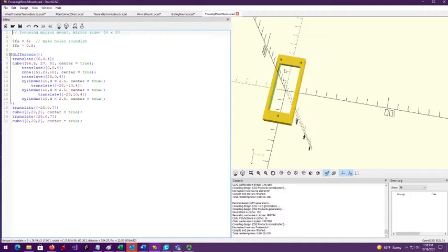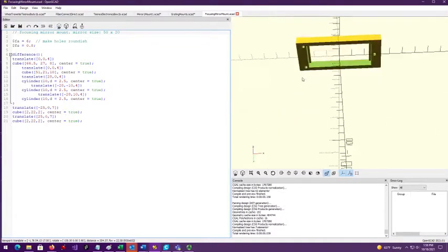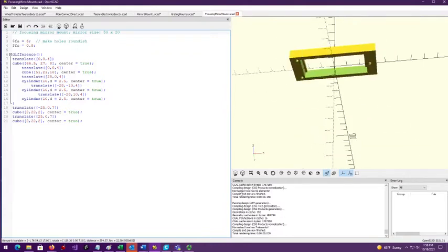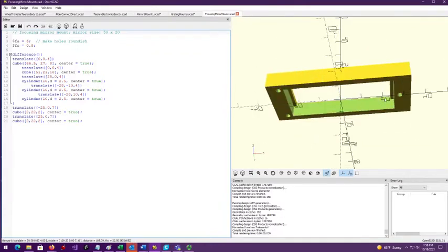All right, the last piece that I have up here right now is the focusing mirror mount. Let's see what that looks like. Okay, the focusing mirror is a 20 by 50 rectangular mirror, and it goes up underneath this thing. Those little wings there, they hold the mirror in place. We have 1, 2, 3 mounting holes.